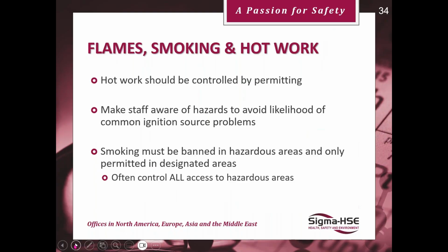Flames, smoking, and hot work. Well, hot work should be controlled by a permit system, a permit to work system. In other words, if someone wants to work with welding, etc., then they must get a permit to work offered to them, and the person that does it must know about the process and know about the risk involved with hot work.